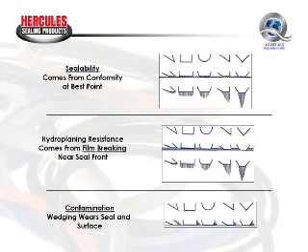By trapping this material, it creates a lot of frictional drag, a lot of heat. The heat softens the seal material, allowing it to extrude even more, and creates a catastrophic failure. In some cases, that pressure trap can be so great that it can actually fracture part of the piston. So when using loaded U-seals on a piston, seal manufacturers design the D-lip so that you have a little bit of leakage on the low-pressure side so you don't trap pressure.